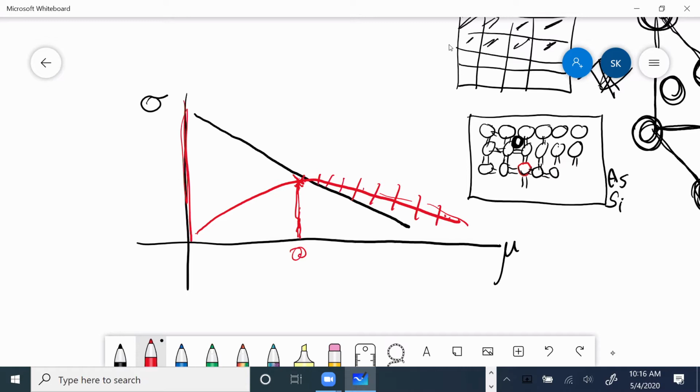Let me look this curve up and come back to you this afternoon. I just hesitated for a moment. It's something similar to that. When the number of carriers increases beyond a certain value, the mobility falls, and so does the conductivity. I promise you, I will look this up and bring it back. You can also look it up in Sze, the book The Physics of Semiconductor Devices, and I shall find it in my notes and discuss it this afternoon.